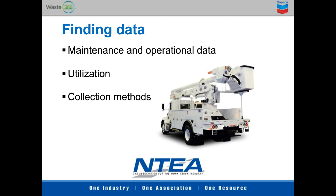Where do we find data? There are several types of data, and data can come from many sources and can be applied over many avenues. This can, as Dan was talking about, affect maintenance intervals, component and utilization. Collecting data on component failures and looking for trends can put you in a position to do some predictive maintenance. But we all know that there are components that have a finite life and eventually wear out. Identifying and replacing these items before they wear out can reduce downtime.